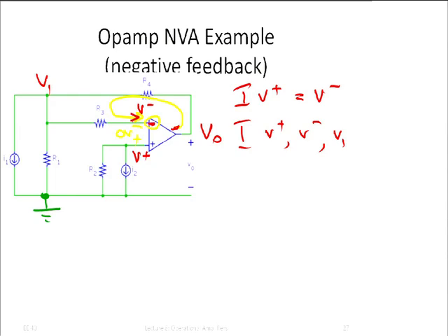This here, that's not a feedback loop. That's actually a very good question. Why is that not the feedback loop? Well, the reason it's not the feedback loop is that this voltage here is ground. Any current, for example, if let's say we put the resistor here, that's a very good question. If we put the resistor here, of course, current flows through this resistor. But will any of this current flow into this node here and therefore provide feedback?